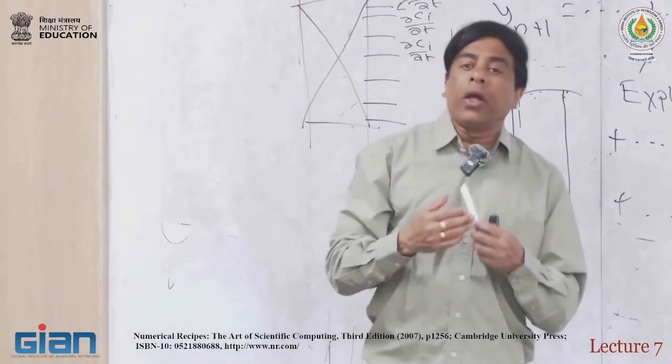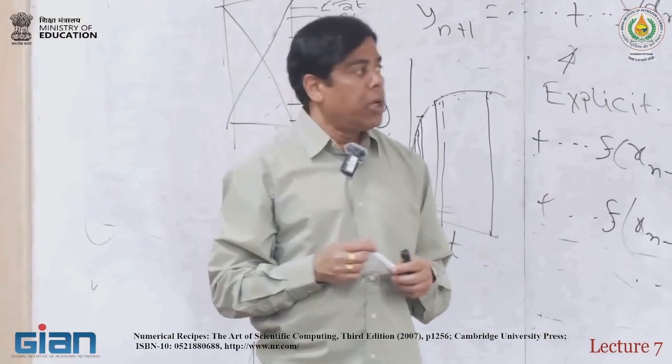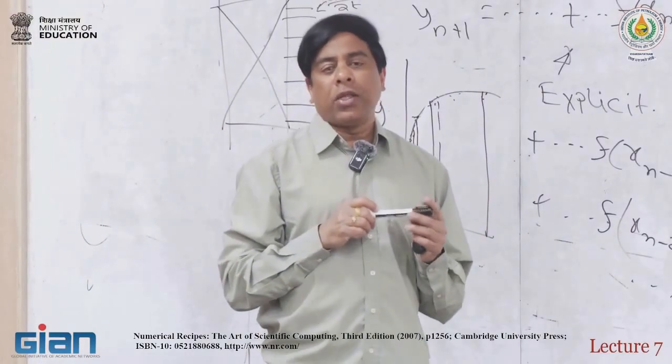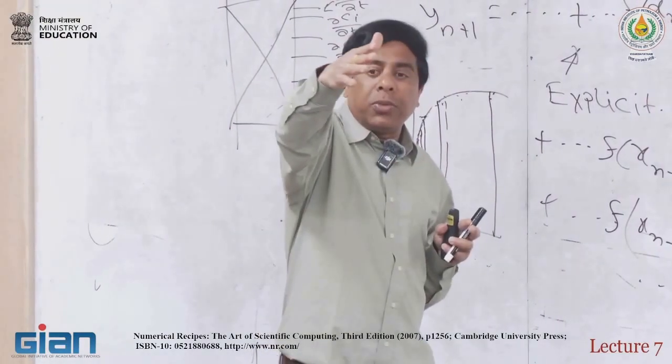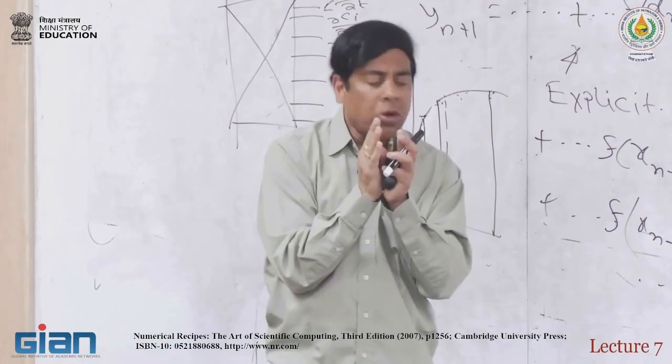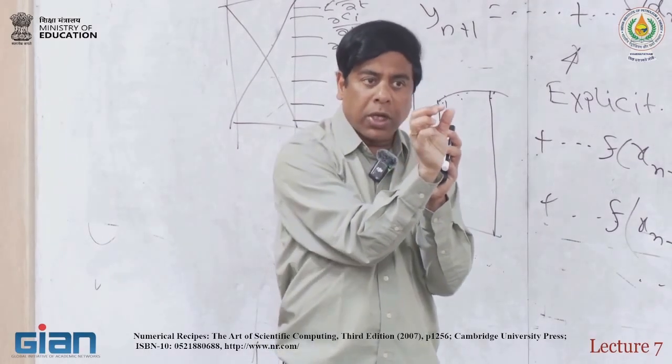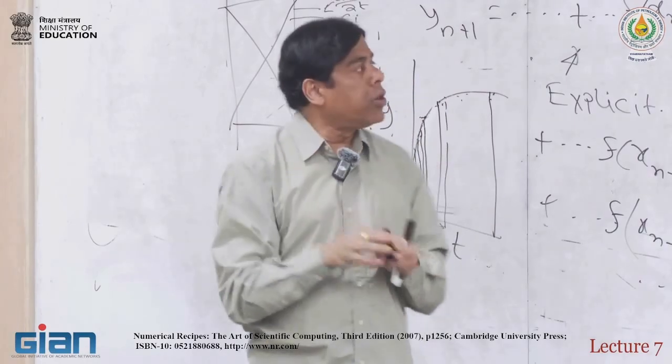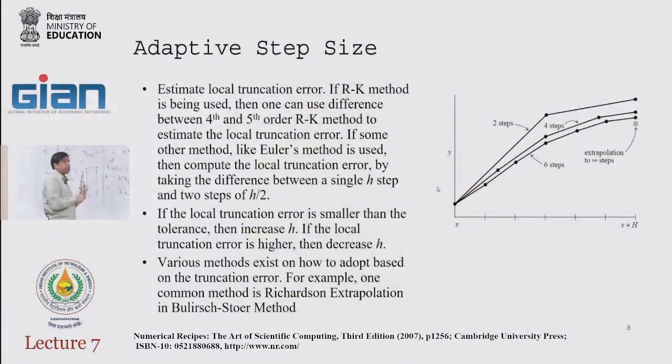That is why you need an algorithm that will tell you that now you can increase the step size, or nope, keep cutting the step. That algorithm is basically the adaptive step size. For an adsorption desorption type of approach, you must always use an adaptive step size solver.